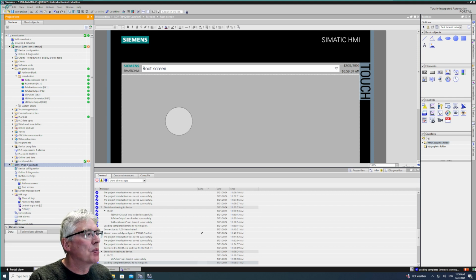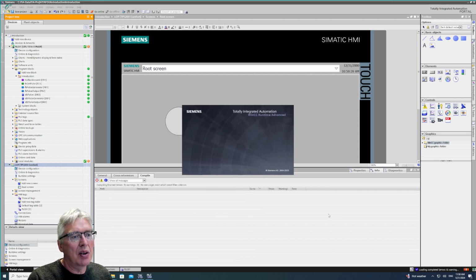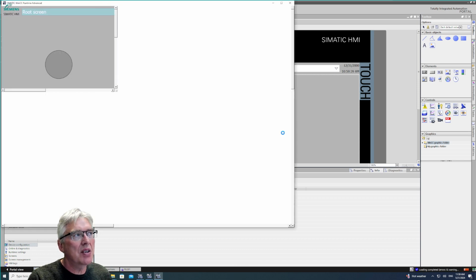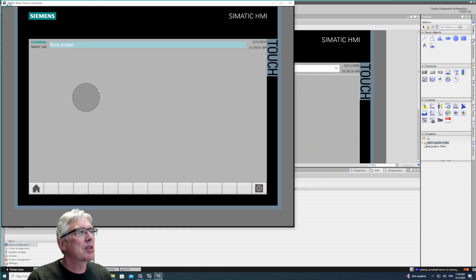And the panel, to look closely. Select the panel. It's the same start simulation. It's start PLC simulation if I select PLC, and start HMI simulation if I select HMI. And let's see. So what it should do, it does a little compile, and now it should open WinCC Runtime Advanced, and so on. It does not flash.